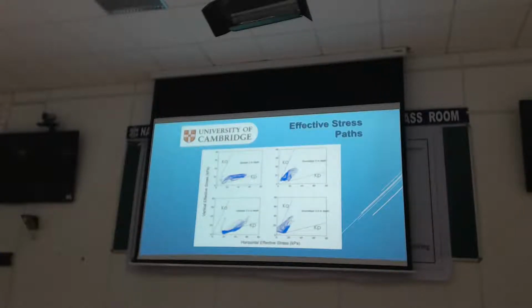Sir, why is it crossing? The pile is going to move more at the top, as we saw earlier, maximum at the top and less at the base. Yeah. So since there is more movement, there should be more force at the top itself.